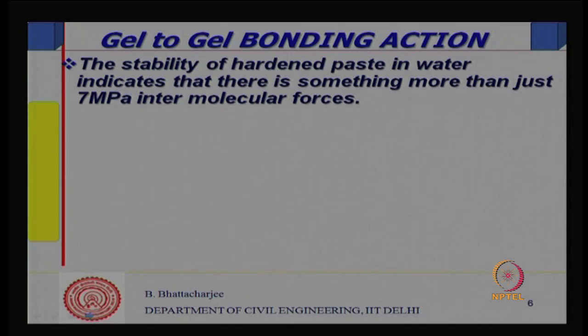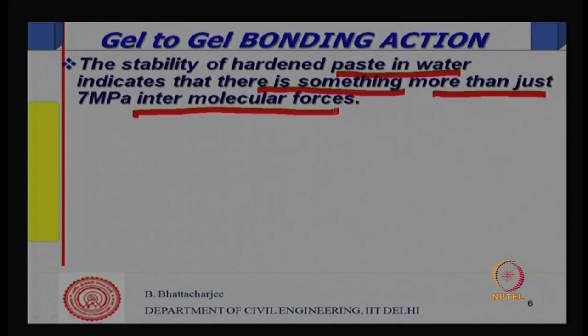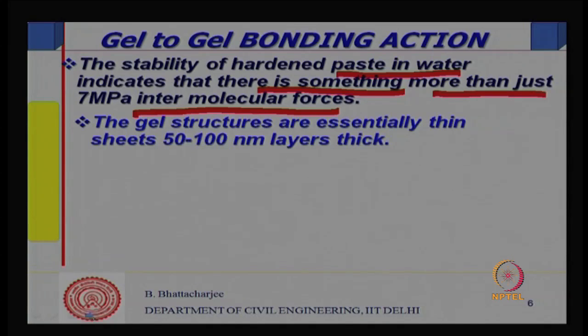Now, van der Waals bonds or intermolecular forces cannot be the only force which is bonding them, but by and large this is the force. So, stability of hardened paste in water indicates there is something more than just intermolecular forces which holds them, but nevertheless that is the major force understood to be responsible for strength of gel to gel.